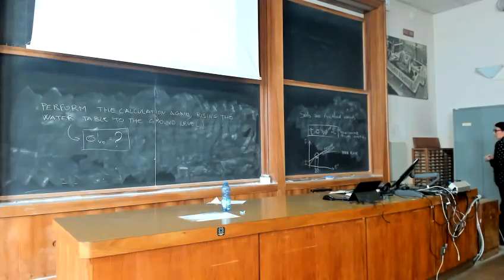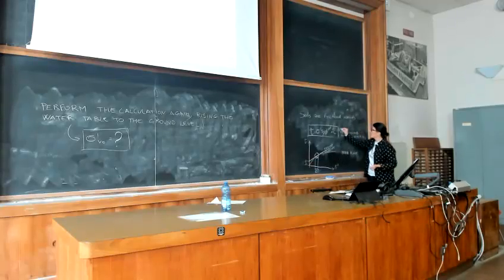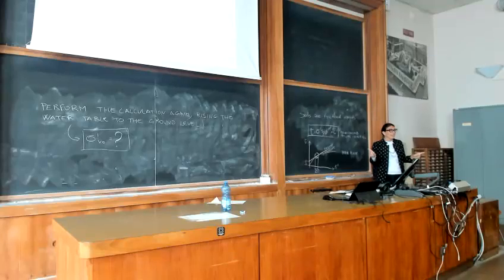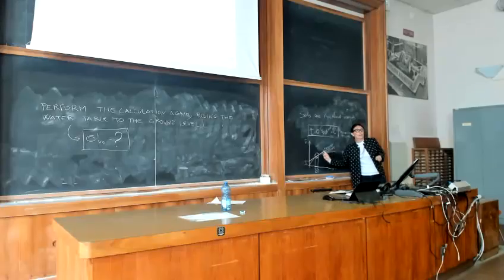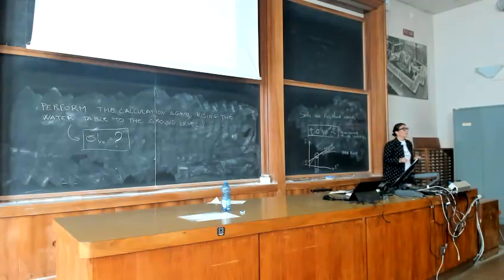So when you talk about cohesion in particular, pay a lot of attention to this parameter because it is not something real. It is a result of a mathematical model, which is our line. The real cohesion usually for soils is 0. So this c dash is called intercept cohesion.